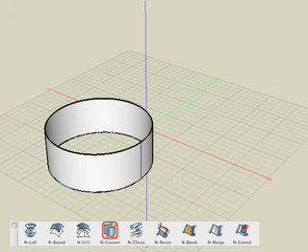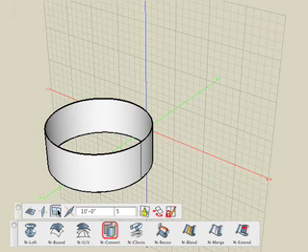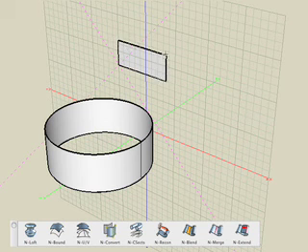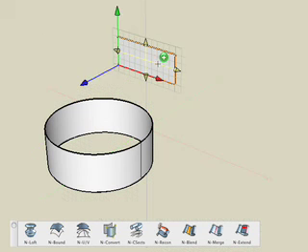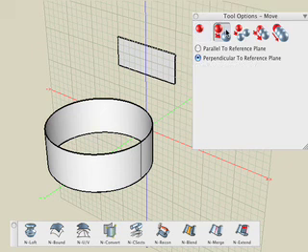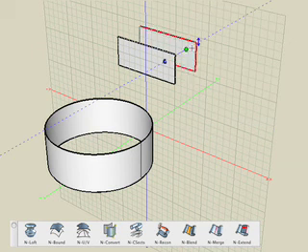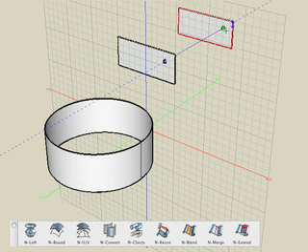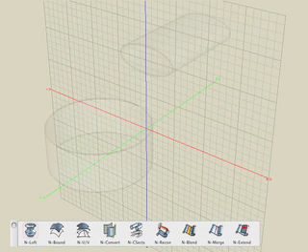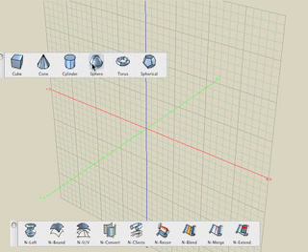For the handle, we first switch to the ZX plane. Then using the 2D Rectangle tool, we draw a 2D shape on that ZX plane. And then we select the Move tool with the Copy option and make a copy of it in the perpendicular direction to that plane. Then select the Nurbs Loft tool and click on the 2 rectangles to loft a smooth Nurbs surface. For the ball of the handle, we'll create a primitive sphere.